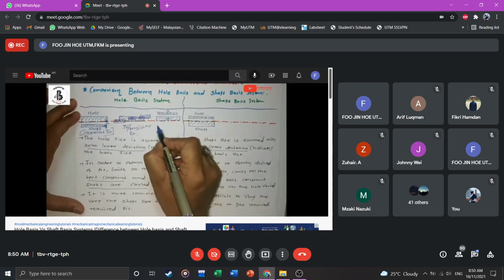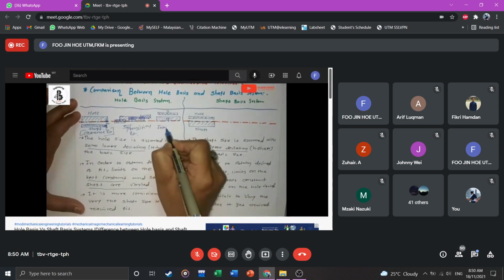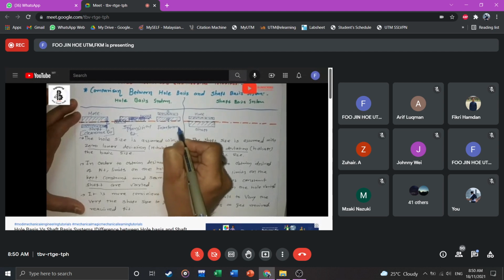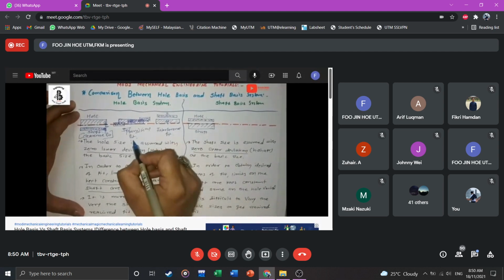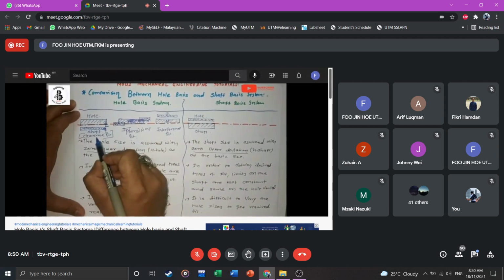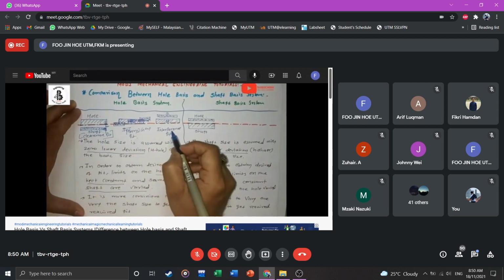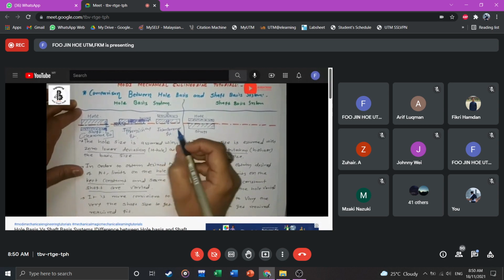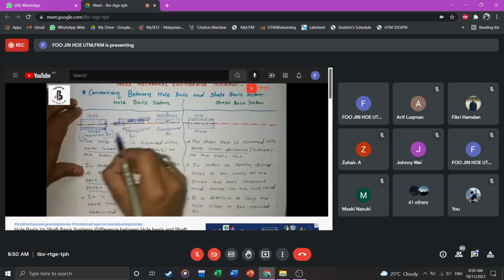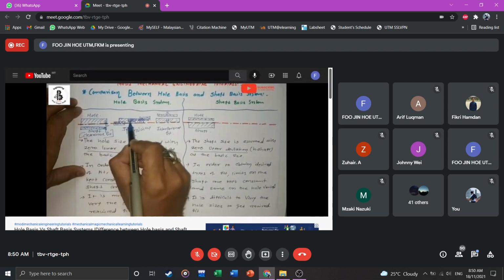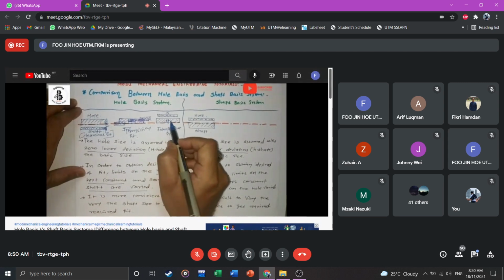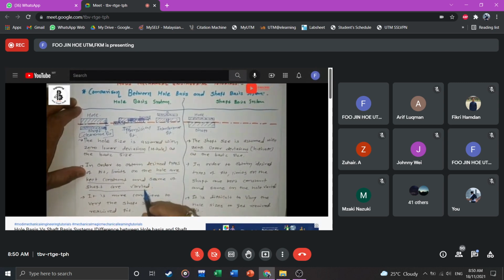That will be called an interference fit. So basically, a transition fit will be the product of either a clearance fit or an interference fit. But these three kinds of fits only change with your shaft dimensions. As you can see, the hole position is kept constant, so you can just change the shaft.